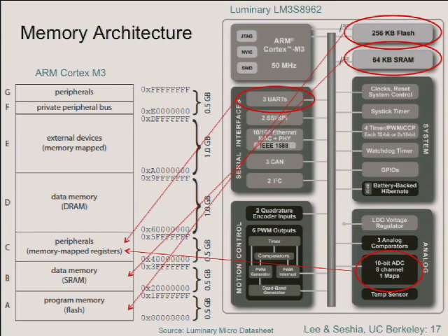And then a private peripheral bus. When you see something like that, that means if you write to those addresses, you're going to really mess things up, or the hardware may not even let you do that. And then a bunch of peripherals. These are the built-in peripherals, I guess, for this ARM processor. So you see these kinds of things a lot when you're working at the bare iron level, and you want to get to the point where you can read them reasonably comfortably so that you can get a sense of what's going on.